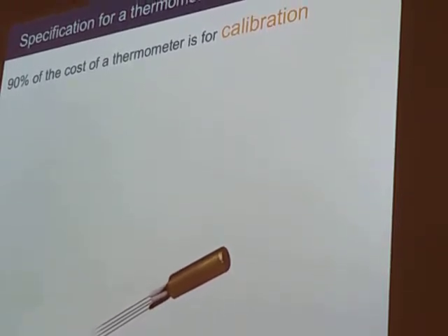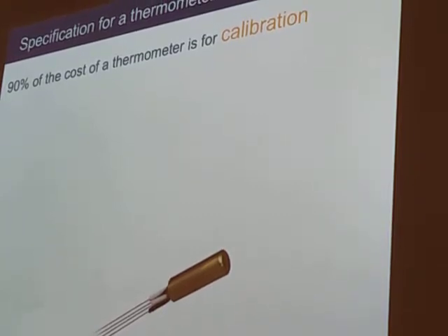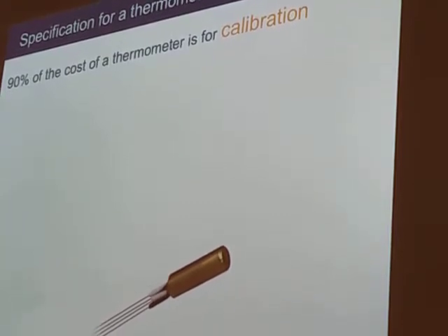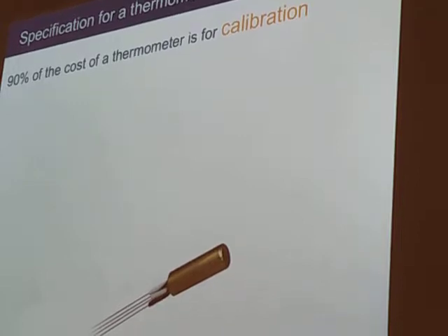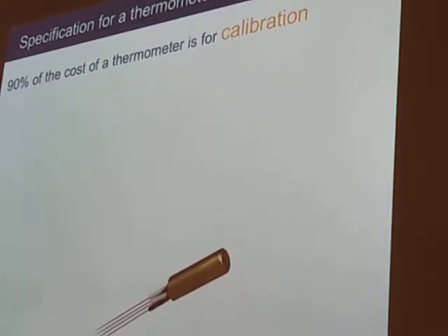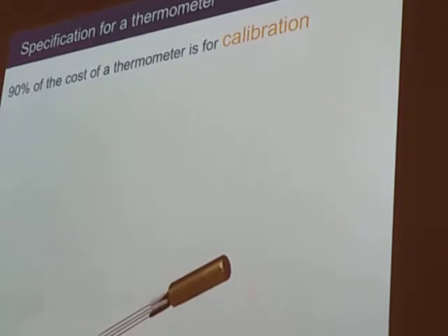Now the problem with these thermometer materials is that the behaviour of electrical resistance with temperature is not 100% repeatable from thermometer to thermometer. It's quite a complicated shaped curve over the full range of temperatures that you could be interested in.